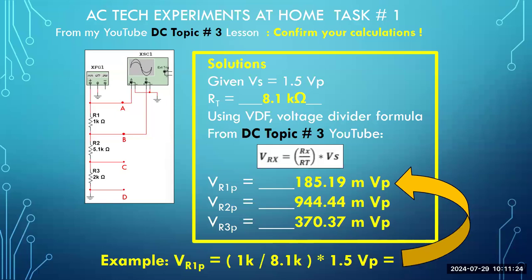Well, welcome back, my friends. Yes, hopefully your answers calculated will compare with what we have on our screen. The R total is the sum of the three resistors that are in series. So 1,000 plus 5,100 plus 2,000 works out to be 8,100, which in proper engineering notation, we will write as 8.1 kilo ohms. The omega symbol is what's used to designate the quantity of ohms. So that's the first calculation you need to make. That's critical. Then we're going to use voltage divider formula and apply it.